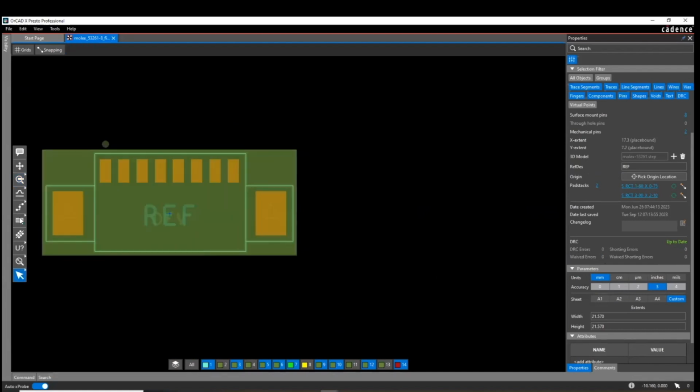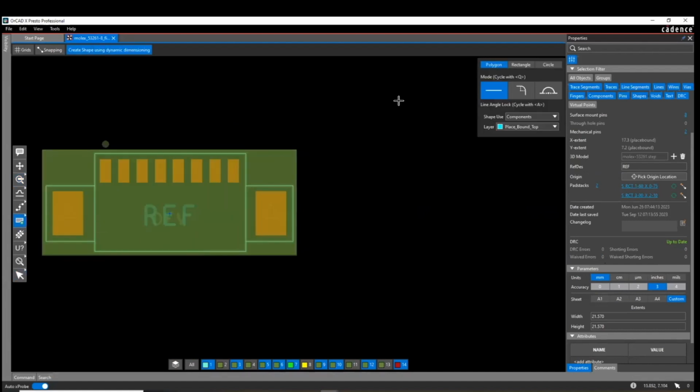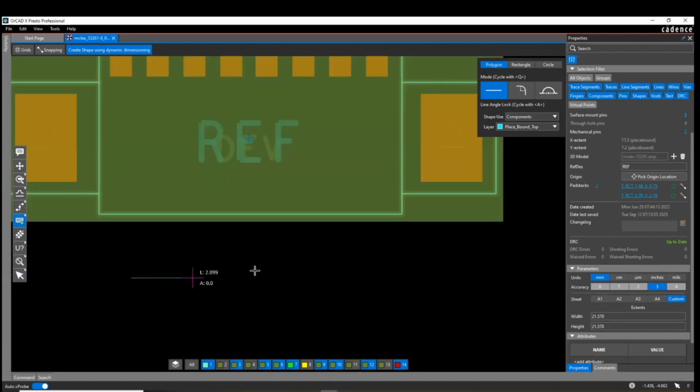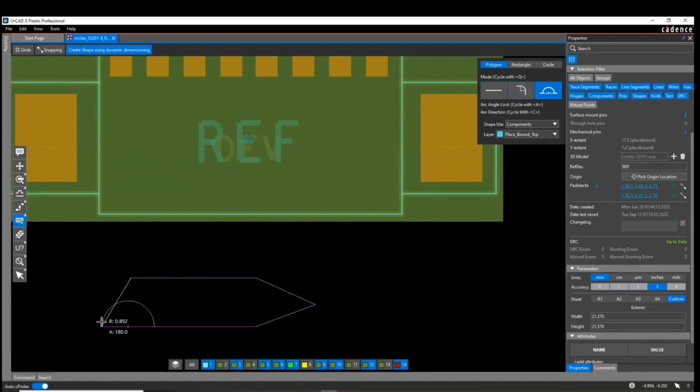Finally, if you want to draw shapes in the pad stack editor, we'll give you a nice drawing shape mode where while you're drawing a shape, you get an on-screen heads-up display of the length and the angle while you're drawing this, and you get nice snapping showing you, oh, that's the snap point of that vertice. This angle is going to be the same as other angles in the design, and you can easily switch from drawing an arc, drawing a half-point arc, to drawing a full arc with the radius and the angle while you're drawing a footprint.